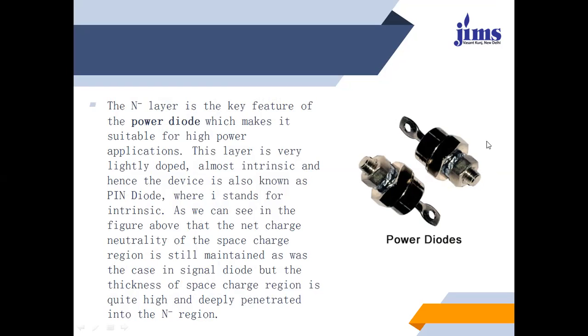This is the figure of the power diode. The external structure of the power diode is simple, and there is nothing different from simple diodes. But from an operation point of view, it is quite different. This layer is almost intrinsic, and hence the device is also known as PIN diode, where I stands for intrinsic.